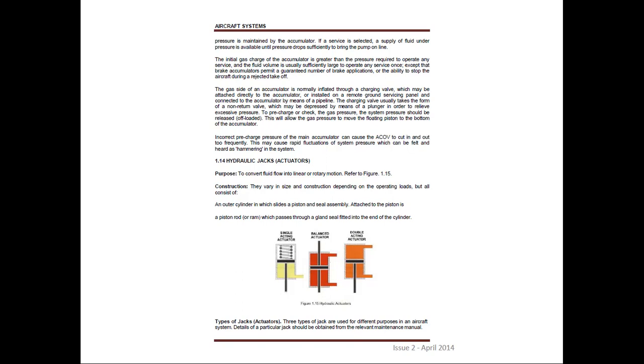So if the aircraft has no power, the brake system, which is a hydraulic system, can still operate with the aid and function of a hydraulic accumulator. That is their job. He also mentioned a charging valve that is attached to the accumulator. It is the same principle as I explained earlier.